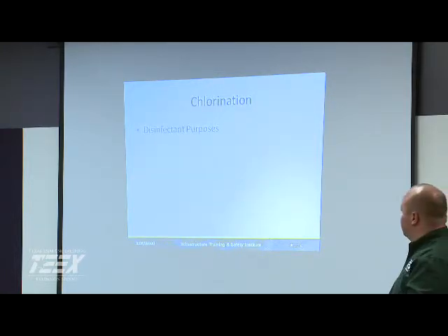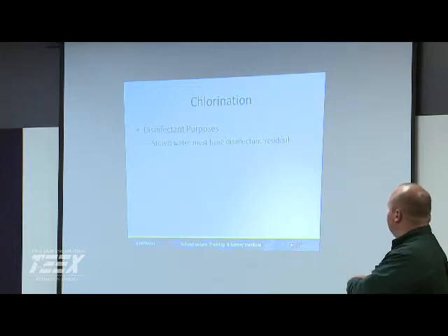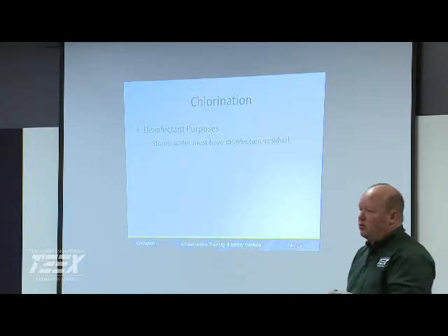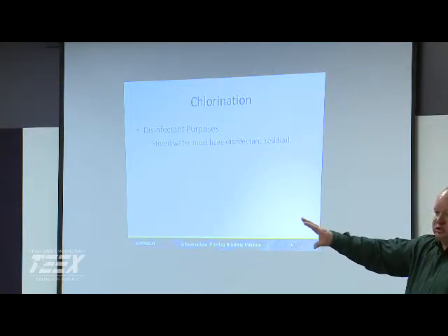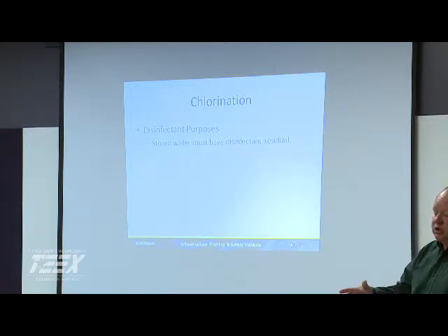Chlorination, what are we using it for? Obviously, we want to make sure that we have a residual for our stored water, not a demand. We're still going to have some demand in the system. We talked a little bit about it yesterday. If you're having problems in your distribution system keeping up your residual, then you've got to look at whether you actually met your demand in the plant.